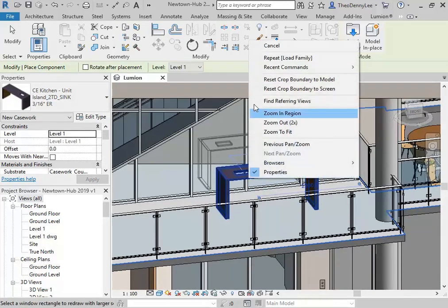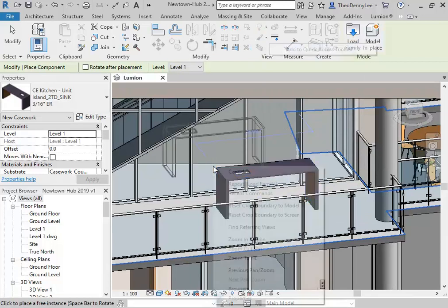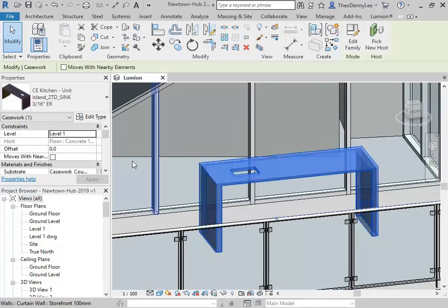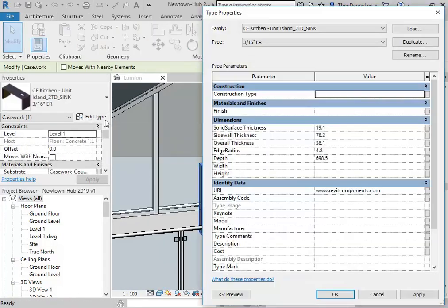So I'm going to put this onto my level there. Yep. And, okay, so if we select that, go to edit type, and no parameter. Now when you see that one, that's one that relies on global parameters, and you won't have the global parameters file to use it. So, yeah, I know it's annoying because it's there always, but you can't do anything with it.